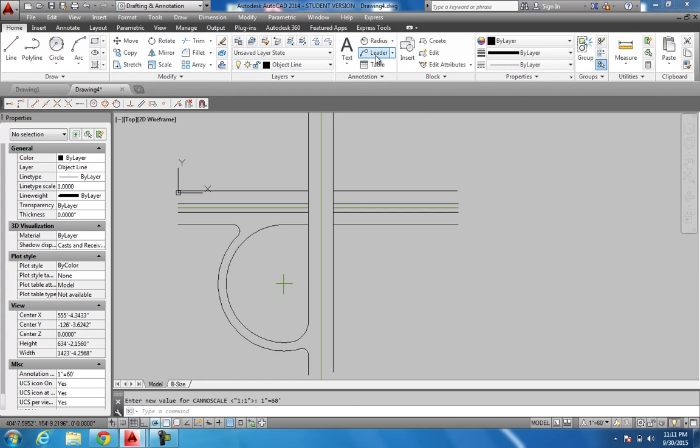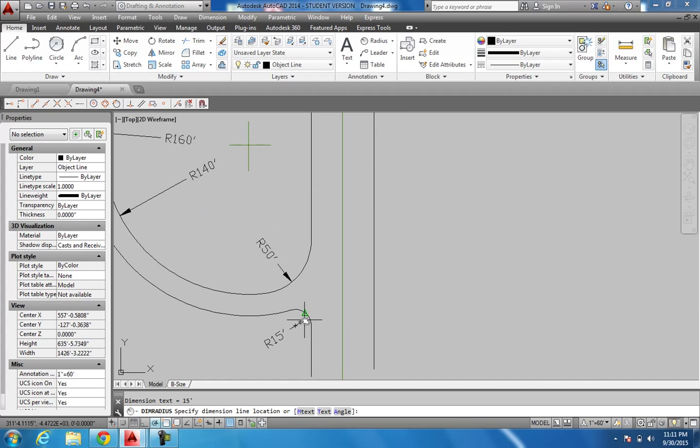Good. So I want to go in here and put my radiuses. Click on this. You kind of bring it back there, kind of makes it look a little better. 140 radius looks good. And this one here, you can put on the outside there, or you can put on the inside there too, just to show it's coming off that center point. 160 foot, space bar, grab this one. Radius of 15, radius of 50. And it's kind of following that around like that.